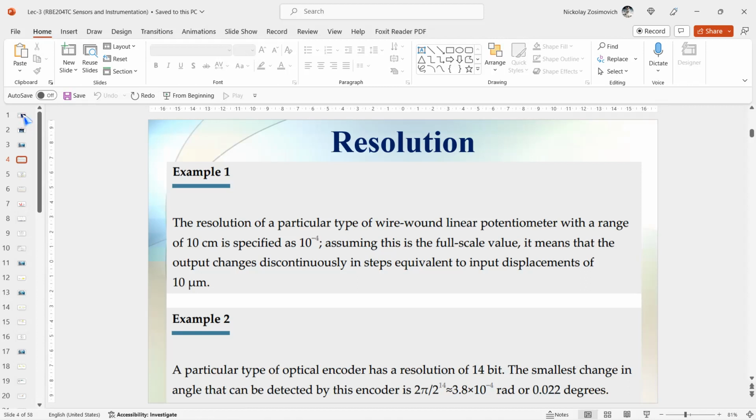Sometimes this parameter is related to the maximum value x that can be processed as a full-scale value, resulting in the resolution expressed as delta x minimum over x or delta x over x maximum. This mixed use of definitions may sometimes seem confusing, but it is easy to see from the unit or the value itself which definition it is.